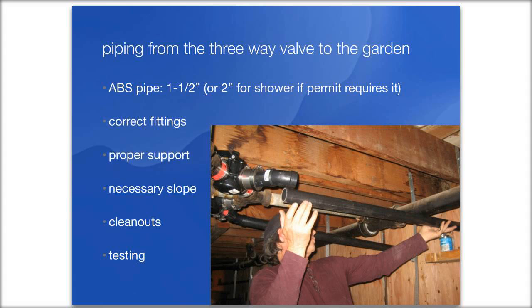Sometimes, and you need to remember that you need to leave space for the actuator. That would be something to keep in mind if you are planning on doing it later, that you install the valve, particularly if you're gluing it in place. Make sure that you install the valve anticipating the size of the actuator that's going to be installed later. And there can be some little tricky adjustments that are made inside the actuator to set it right.